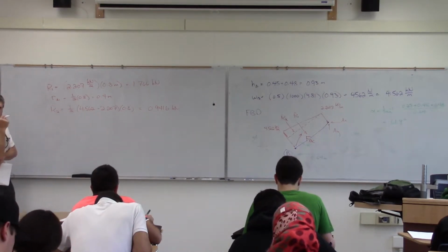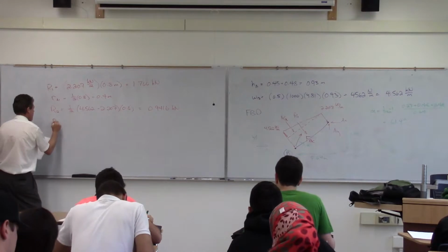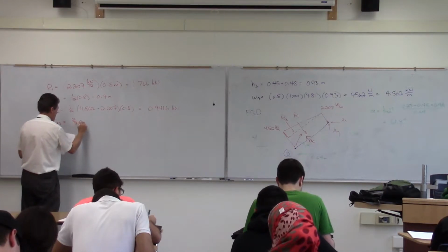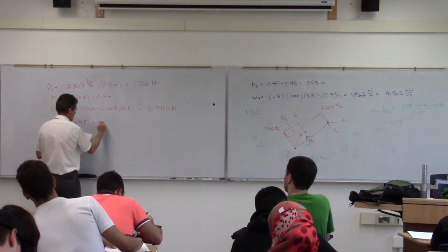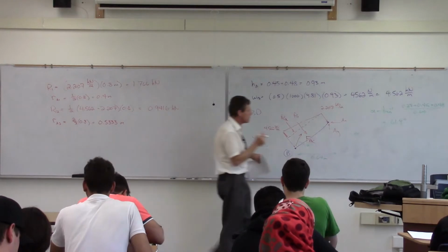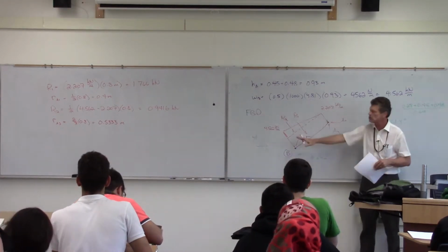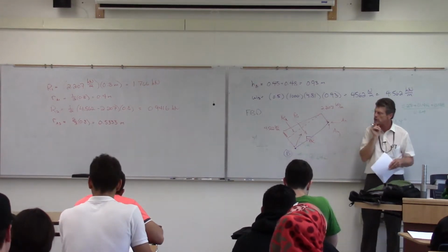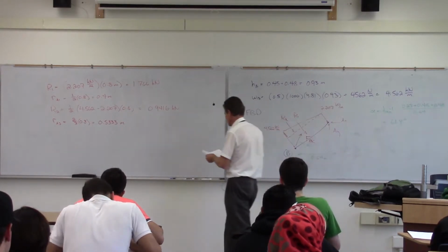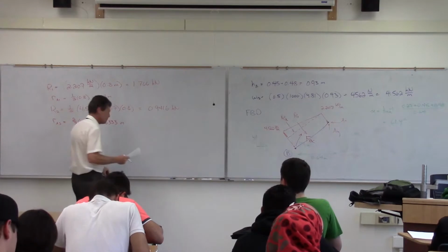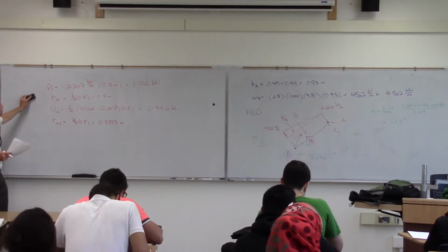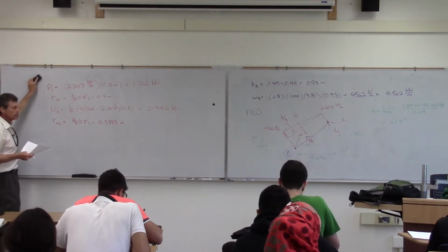It'll be just a little less than 1 kilonewton. And then again, I'm going to be taking my moment from A there, so it's going to be 2/3, since it's 1/3 up from the base of the triangle, or 2/3 down from the top. Everybody got this? I'm going to keep that up because I want to keep the picture up.